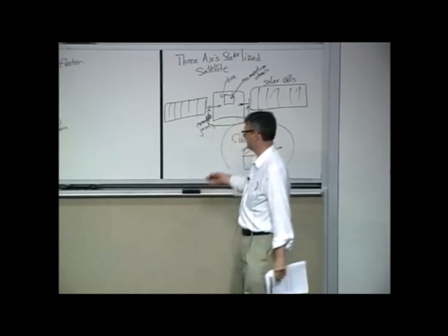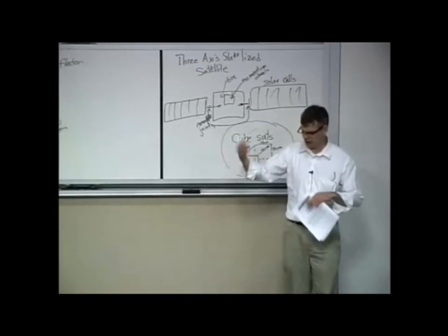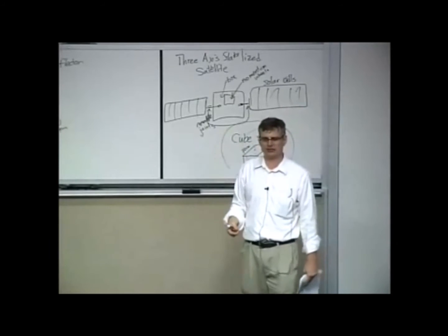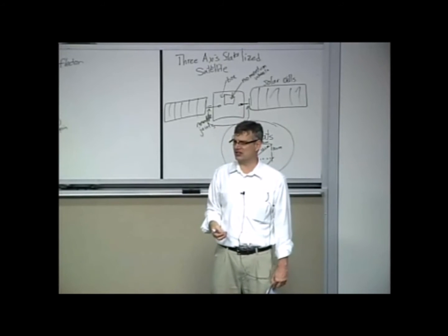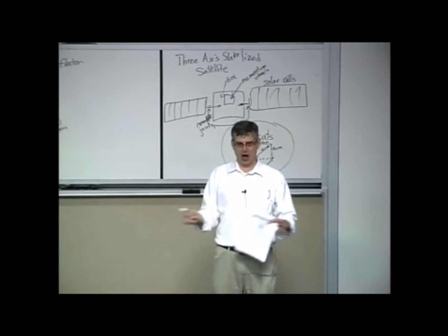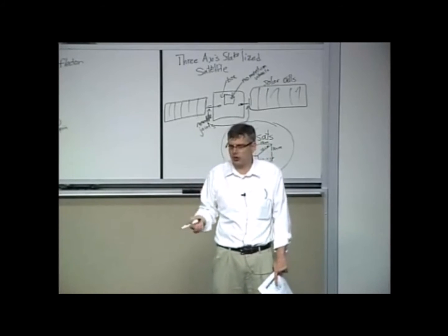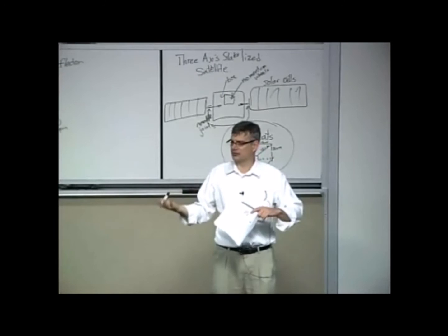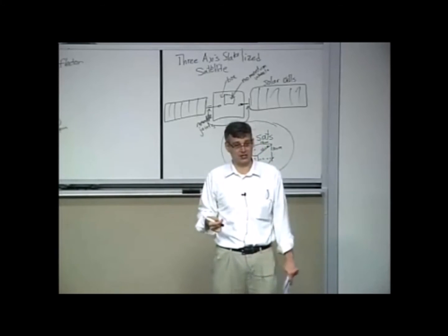And so this is a common third architecture. The CubeSat usually just tumbles in space, so you use something that's not particularly directional to do communications, something relatively omnidirectional, which we're going to learn really hampers your link budget. But if you're in low Earth orbit and you've got enough signal processing and you're not taking up too much bandwidth, you can do communications with that.